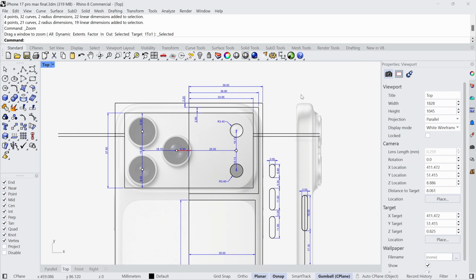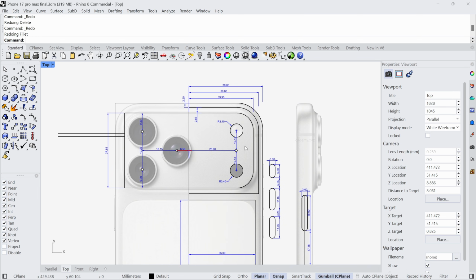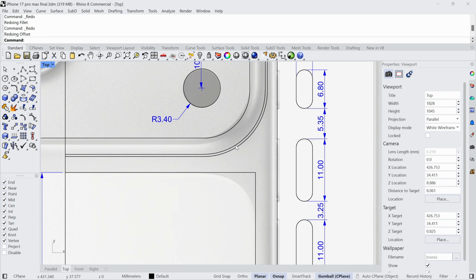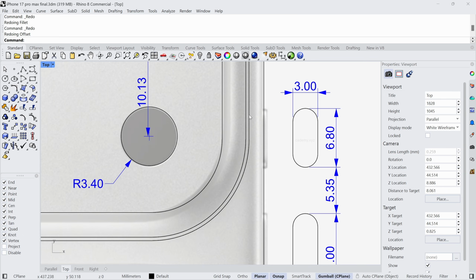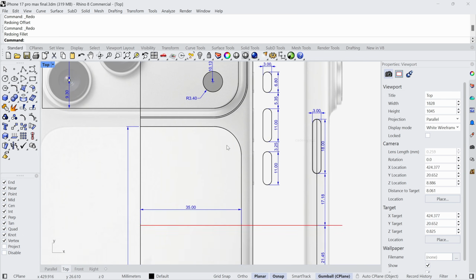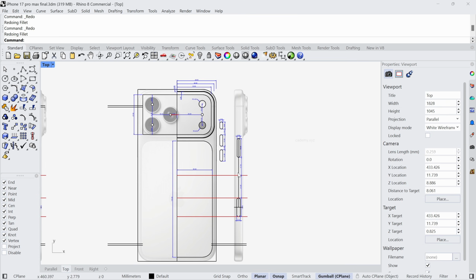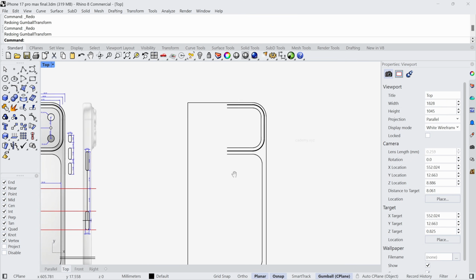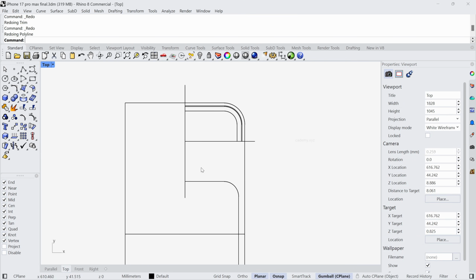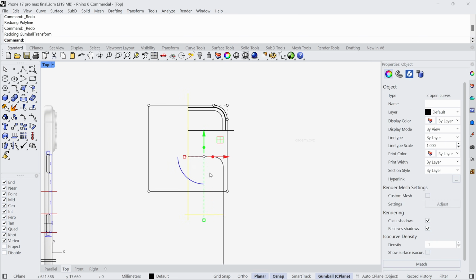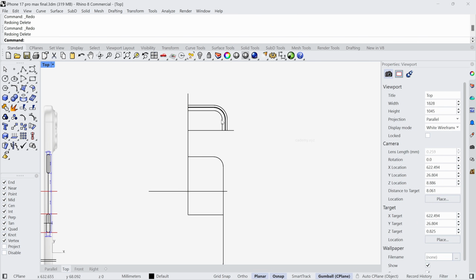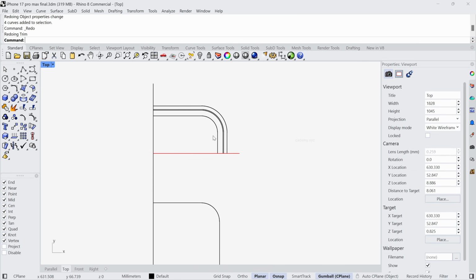So to apply the fillets, we will use some reference radiuses. I will annotate it in a moment, and we will define the radius for the camera part, the transition part, and the outer boundary. We will also create an offset curve so that we have a flat section between the two transitions. I will do the same thing for the other wireless charging part. I'm making a copy of it and I'm trimming the excess bits because we just want a symmetrical part, and we will just mirror the remaining curves after we have fixed these G1 boundaries.